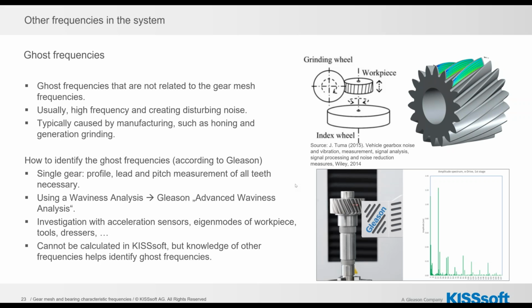Another topic that needs to be covered when we speak about the drivetrain frequency is the ghost frequencies. I need to emphasize that the ghost frequencies are not related to the gear mesh frequency in the current design, but they are usually high frequency and create disturbing noise. They are typically caused by the manufacturing, such as honing and generation grinding, and this could be connected to, for example, the index wheel on the grinding machine, which typically has quite a lot of gear teeth, around 190 or even 200, and then we have some grinding wheel which operates on the workpiece,